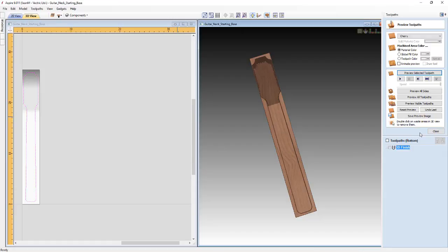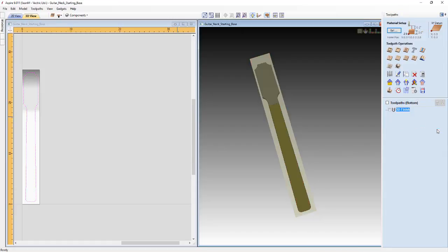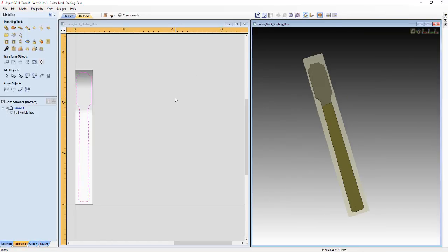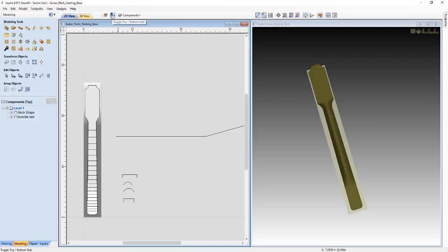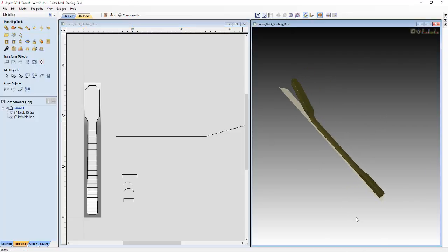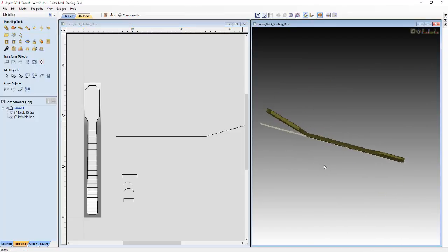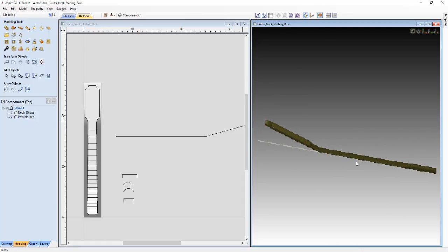So how we do that is if we go over to the modeling tab again, so I'm just going to go back from the toolpaths by pressing this to switch over to the design side. And first of all I'm going to start by going to the top. So I'm just going to switch the icon here to the top side, like so. And what we need to do really is decide how much we want the tool to go past where it was originally cutting to. And I'm going to just choose a very small, minute amount of just 1/10 of an inch.